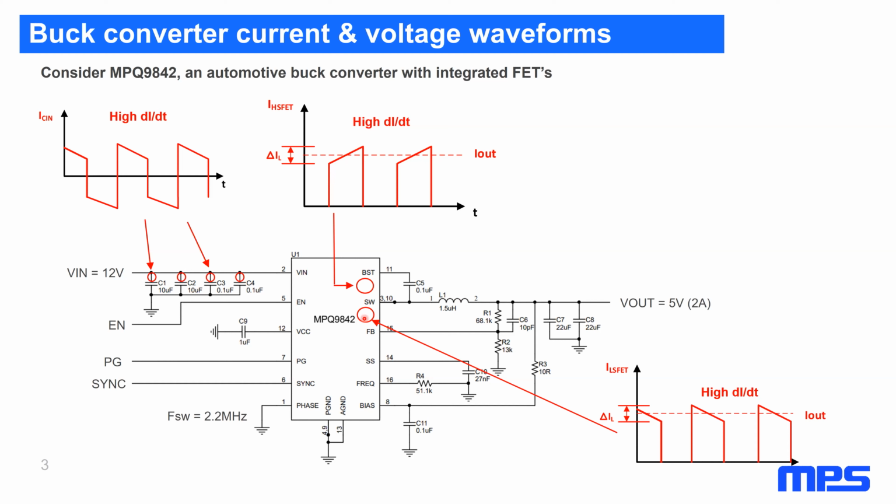And the low side, on the other hand, turns on when the duty cycle is in its off cycle. So this will be the slope of the ramp that decreases related to the inductor current. And then it goes to 0. Then when the high side turns on, this is at 0. Low side turns on, this goes back on, and it continues.